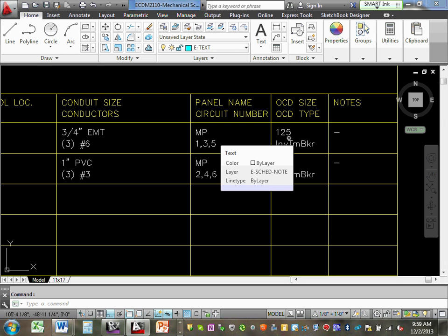And you have to provide a mechanical schedule for the mechanical contractors. That mechanical schedule will be shared with them, so they know what their responsibility is and what our responsibility as electrical engineers is. It's so important, guys, because it ties the mechanical part to the electrical part. It is duplicate. You're absolutely right. So as you do the schedule, you can go to your panel schedule and get some information directly from it if you finished it.